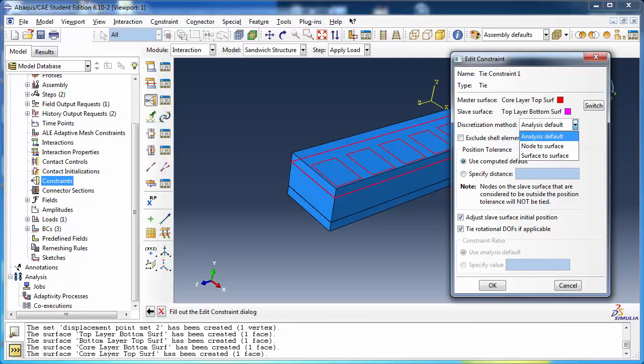The surface-to-surface tie constraint differs from the surface-to-surface contact in that each surface-based tie constraint involves only one slave node, whereas contact involves multiple slave nodes. As with contact, the surface-to-surface formulation results in a more uniform distribution of pressure and less stress noise at the tied interfaces compared to node-to-surface. The disadvantage is that it's not as efficient as node-to-surface. Node-to-surface, on the other hand, is more efficient. However, the forces will tend to concentrate at the nodes, leading to spikes and valleys in the stress distribution.